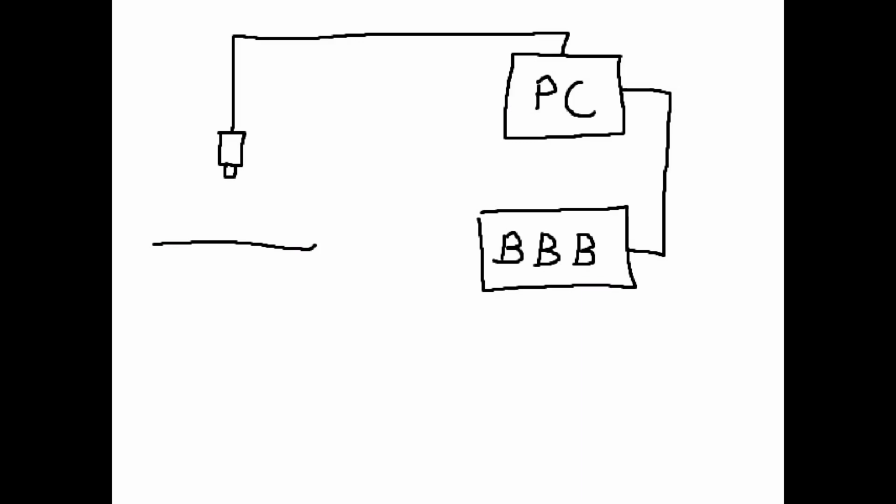If the motor driver is attached to a pulse width modulation port, then the action module can directly activate an appropriate stream of pulses. If the motor is something like a stepper motor, the pulse width modulation port could be used for that as well, since the frequency is also variable. However, the pulse width modulation ports on the Beaglebone Black are limited in number, so the action modules interfacing with stepper motors typically interact with an assembly language program developed for the TILO project, which runs in the Beaglebone Black's programmable real-time units.